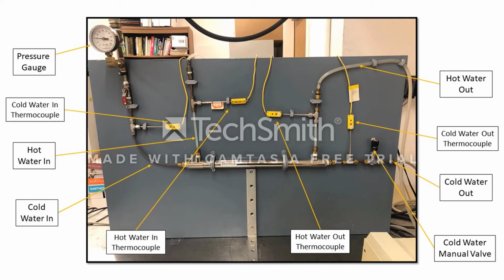Before we perform these experiments, first we are going to put the set point at 5 degrees above that cold water temperature. We're going to put the system into automatic control and input that KC and tau I value for whatever tuning set we are going to be testing. We need to let this tuning set reach its steady state, and then once it reaches that steady state, we are going to mimic a disturbance by turning that cold water valve from the 5 to the 50 position, and then we'll see how the system reacts. We'll collect data until it reaches that steady state point again, and then we are going to repeat these steps for, again, the slow, the normal, and the fast tuning sets.